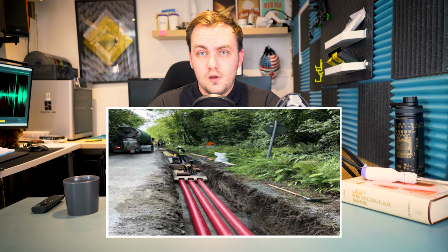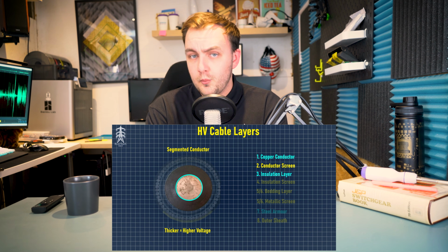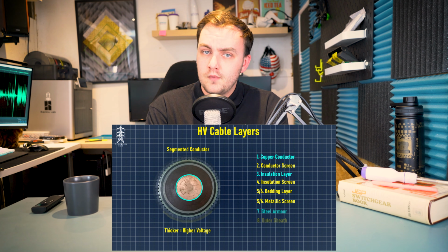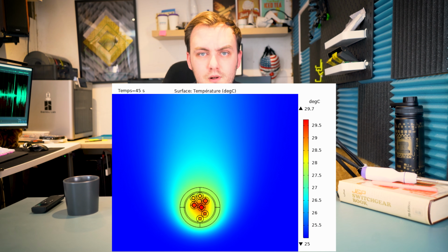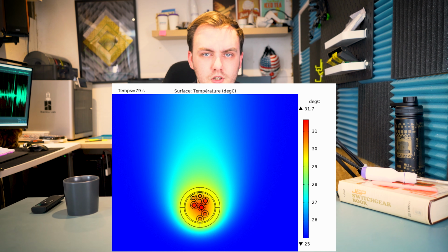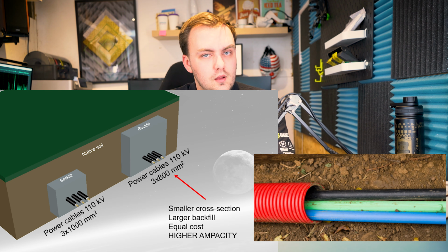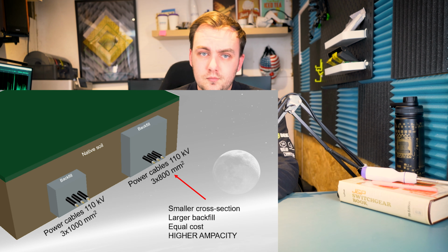So why does this all affect cables especially? Well, cables are often buried underground, in thick layers of insulation and armouring around their conductors. This insulation is essential for safety, but it also traps heat, reducing how well the cable can cool down. And that's why we perform detailed thermal analysis when designing cable routes to ensure the surrounding materials like soil, ducts or thermal backfill can absorb and carry away heat.